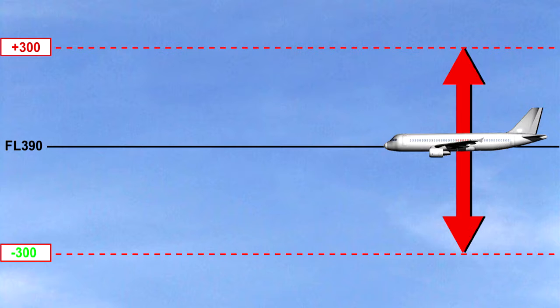Ground controllers will require confidence in the SSR accuracy of an aircraft, and an aircraft will be considered to have reached a flight level to which it has been cleared when 3 consecutive renewals of the Mode C level derived information have indicated that the aircraft is within 300 feet of the assigned level. In this manner, all aircraft using a piece of airspace will be accurately tracked. This completes the lesson on general radar services.